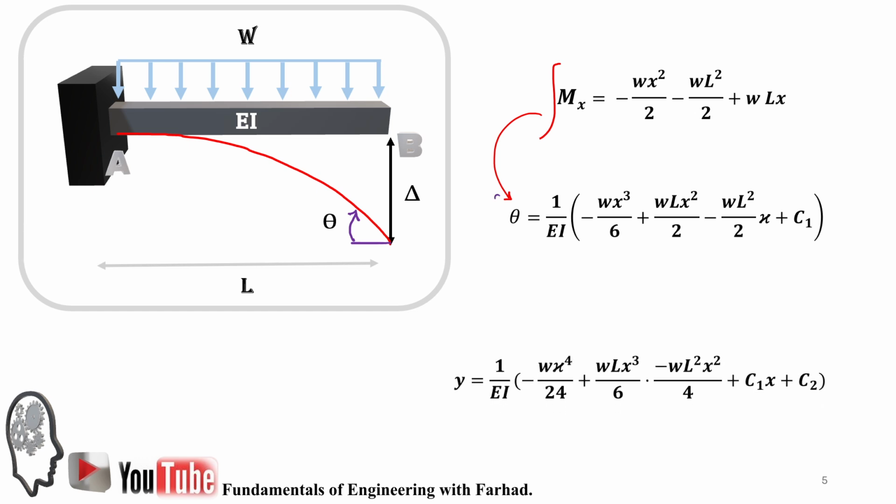and by integrating theta, it gives us the deflection function, and you can calculate it for any point on the beam because this is just the function. By each integration, a constant comes into our equation, C1 and C2. So by two consecutive integrations from M sub x, you will reach the delta function.